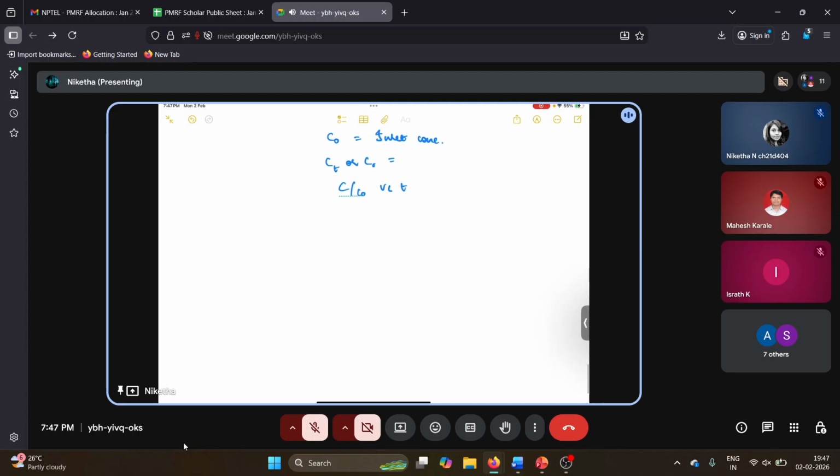And then we have breakthrough curves. Breakthrough curves will tell us where the breakthrough point is coming, and based on that we can design the resin. And based on that we can calculate how much volume of resin will be required, and for treating how much volume of wastewater.